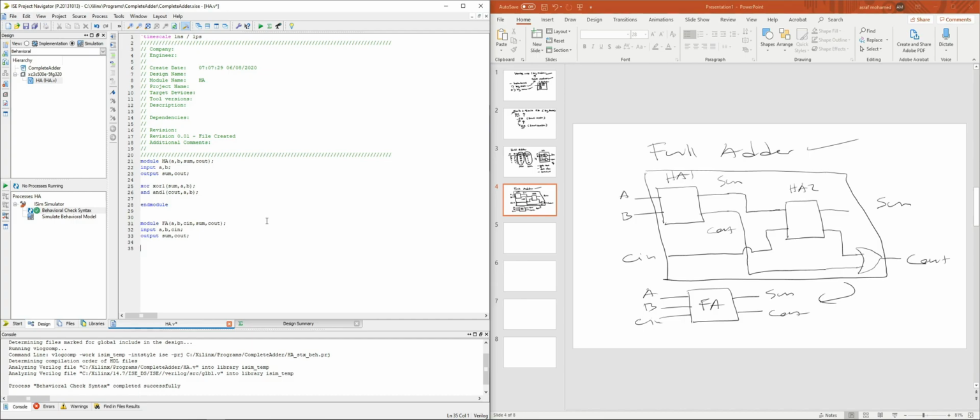How are you going to call the half adder? You come here, copy this particular line, Control C, come here, Control V. Now give a special name, half adder 1. This is the module name, then you assign a unique name to this instance, because you have 2 different instances, half adder 1 and half adder 2. Your task is to connect half adder 1 to half adder 2.